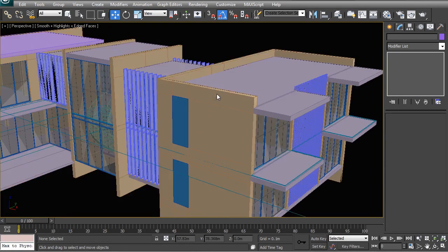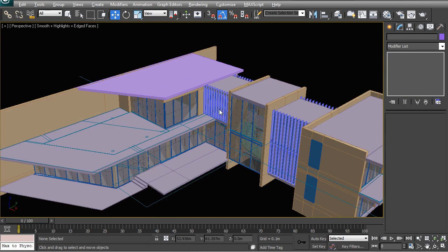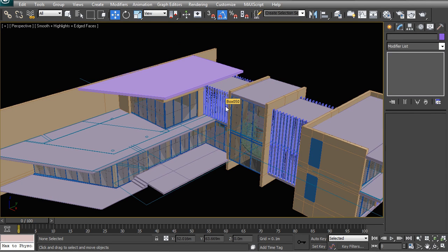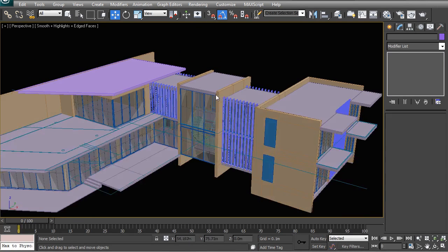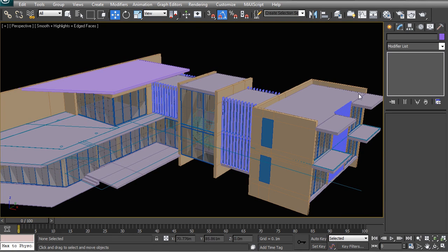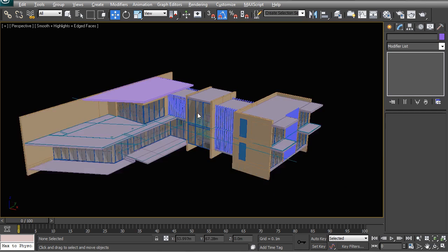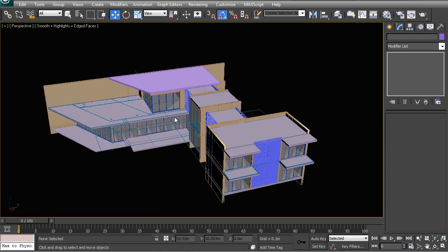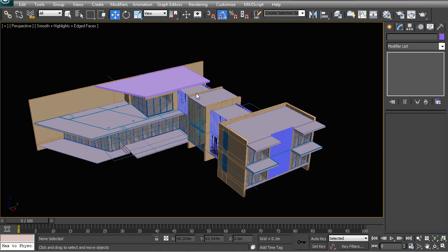So that is it for this lesson. We have gone and made all the roof slabs. We have looked at some of the spline editing work, in other words, deleting vertices, creating lines, and basically editing and reconfiguring these editable splines to make the roof slab from existing objects that we've already made for ourselves. And this often is much, much quicker, as you have seen, than actually doing everything from scratch, especially if you don't have the exact roof plan where you can very simply trace that outline in one go.